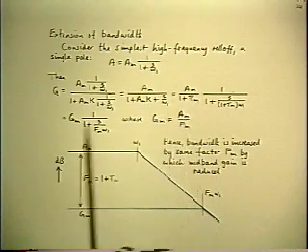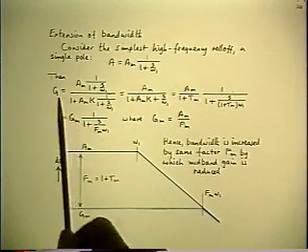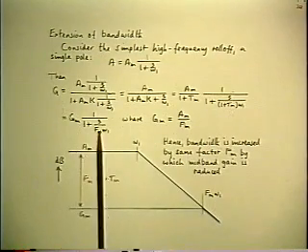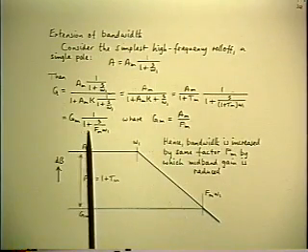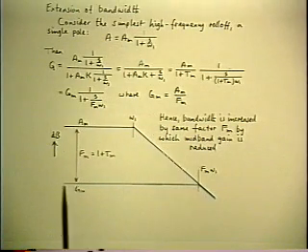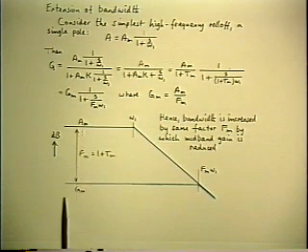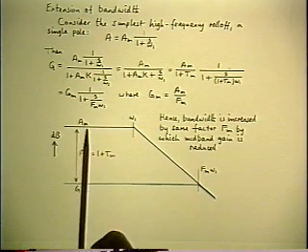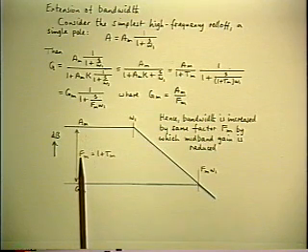And you identify those flat gains as the coefficient in front is the midband value of the closed loop gain, which is GM, and the pole is the pole in the closed loop gain, which is FM times the pole of the open loop gain. So down below, I've sketched the two gains, the open loop one, which is the blue line, and the closed loop one, which is the green line. And of course, the midband values satisfy the basic relationship: closed loop midband gain is the open loop midband gain divided by the midband feedback factor.